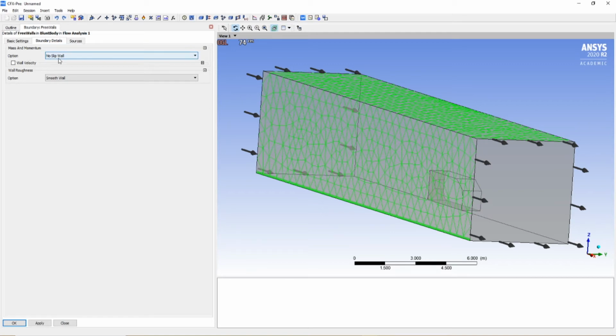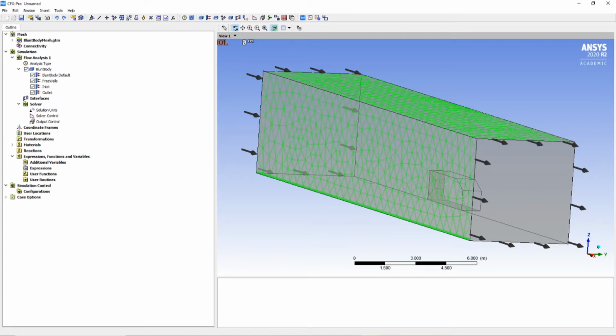The default condition is the one in nature, where the fluid, as it gets closer and closer to the wall, its velocity starts to slow down until it reaches the velocity of the wall, which is generally 0, especially if you think of the sides of a channel or the walls of pipes. So we're gonna change the no slip to the free slip condition, and click OK.